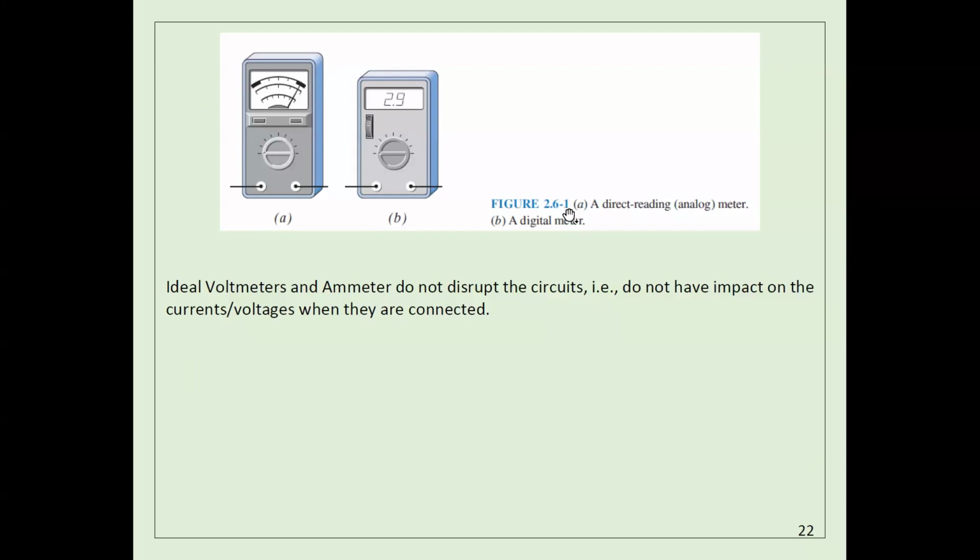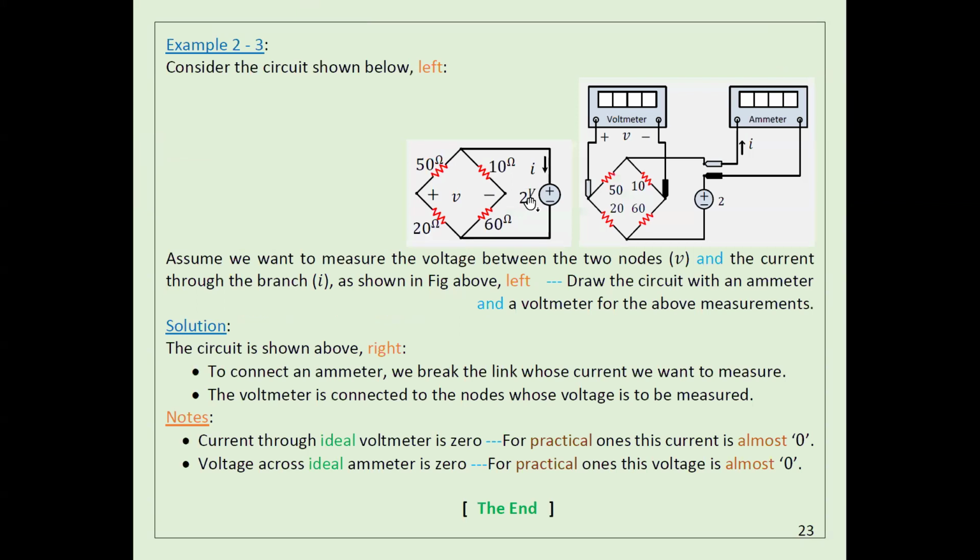Okay. So anyway, here you may be familiar with some of these devices. I think most people now are using digital ones, no one is using the analog devices anymore. So for example, the last slide in this chapter is a very simple one. I just want you to know how you connect, because the way you connect the voltmeter or ammeter is different.